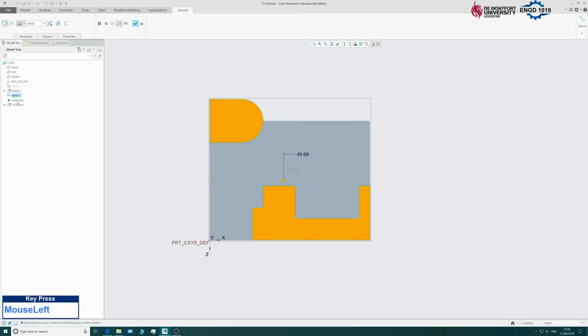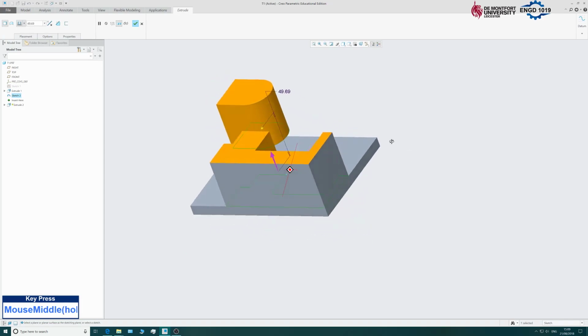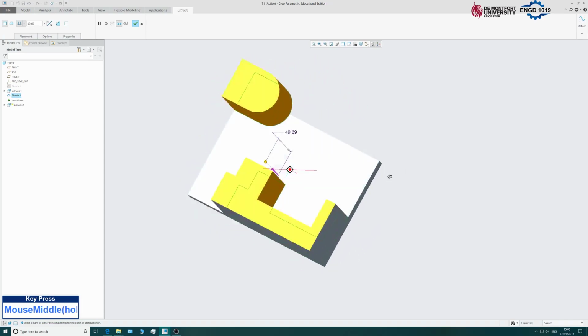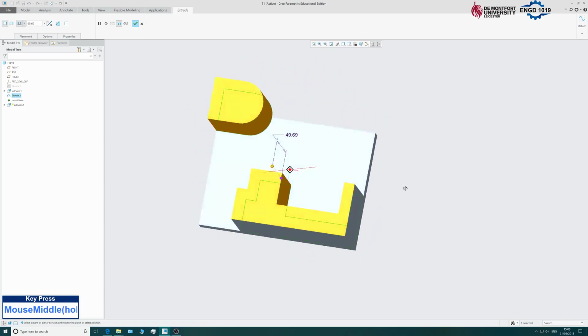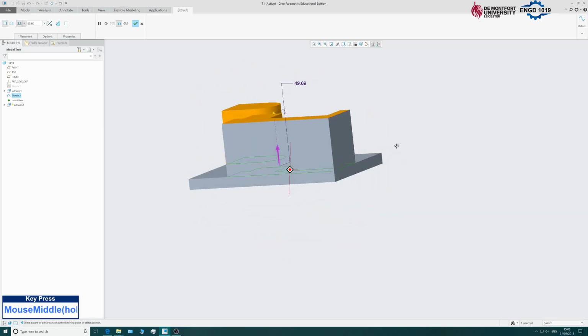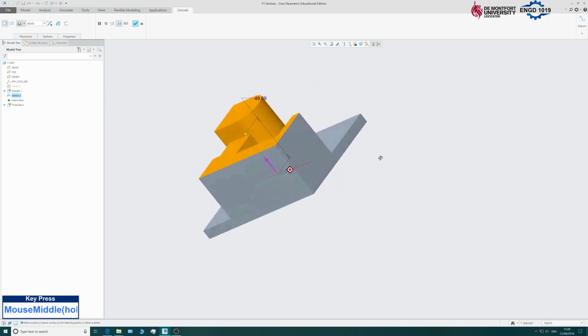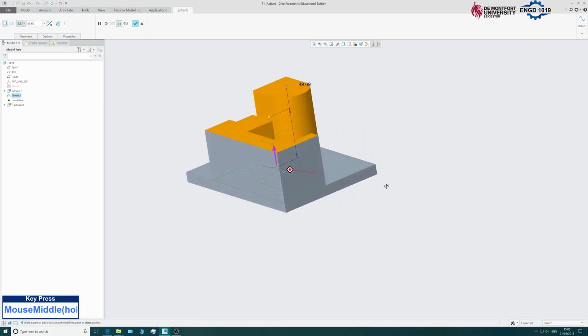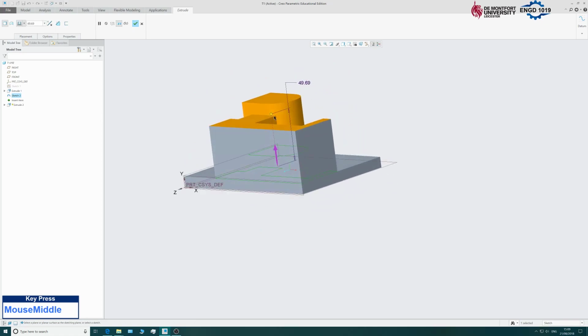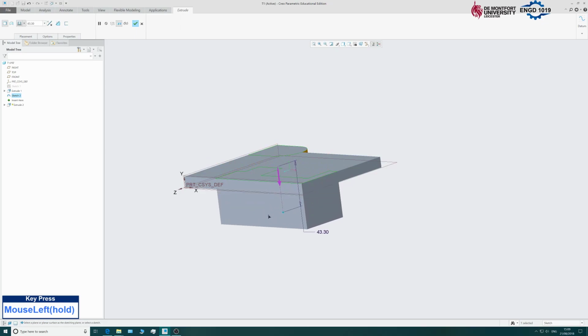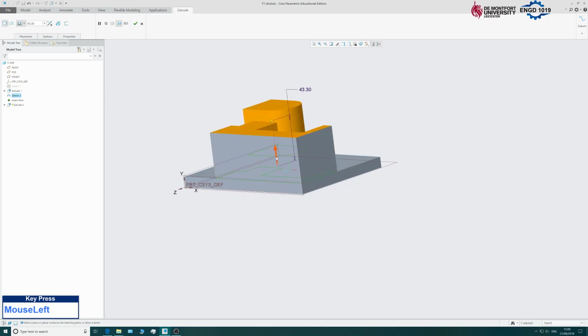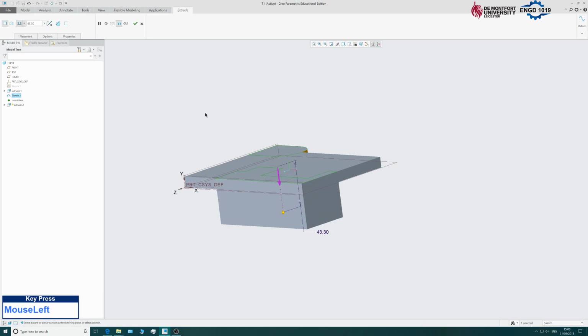And so I had the sketch highlighted, I pressed the extrude tool, and you can see here that what it's trying to add the material. So that's not what we want, we want to remove it. To do that, I'm going to flip the direction. To flip direction, you can drag this and move it below, or use the arrow to flip the direction.